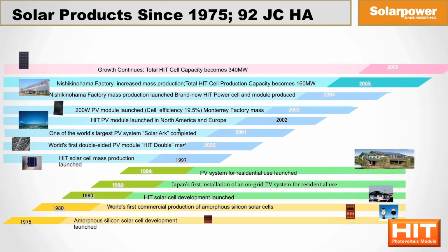Lo and behold, it produced what's been at times the world's most efficient solar cell. One way to look at that is you get typical efficiency of 14 or 15% in the monocrystalline world. Thin film or amorphous can add an additional 6 or 7%. Technically, that's the absolute wrong way to look at how it works, but it helps you remember that's the effect. By combining the two, you get something closer to a 20 or 21% efficient cell.